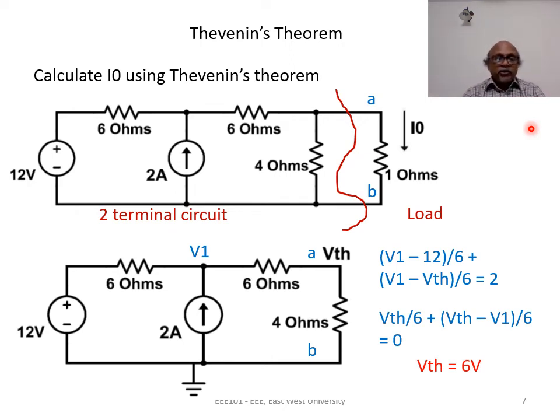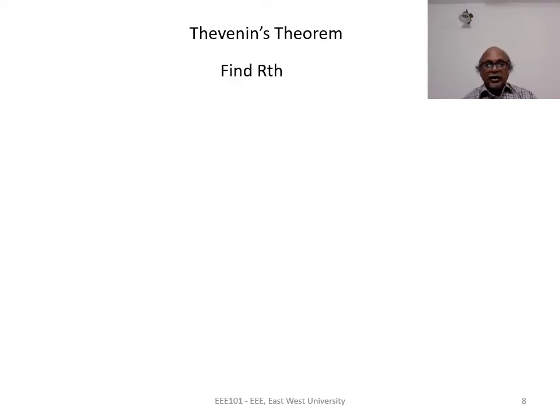Usually, you don't need to apply multiple techniques to determine RTH, but to test our knowledge of RTH calculation, we will calculate RTH of this circuit using all three techniques and then we will verify if we get the same result. Okay. First, we consider case 1. In case 1, we deactivate the independent sources and find Req.